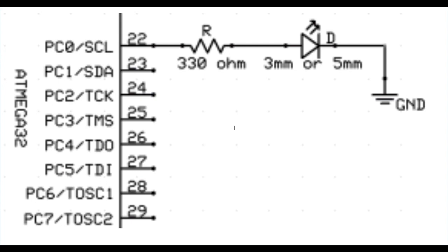In this example we are going to see how to interface a LED to a microcontroller and make it keep on toggling, or blinking. So here we have a LED connected to the microcontroller through a 330 ohm resistor. Here in this microcontroller, if logic 1 is popping out, then it will make the LED glow. If logic 0 is popping out, it will make the LED turn off.